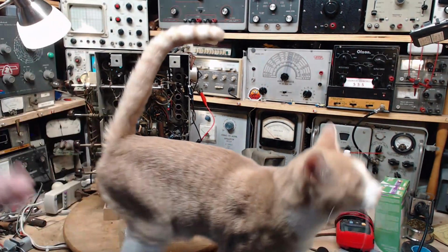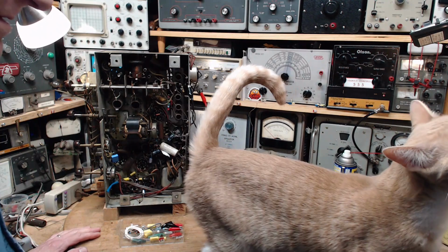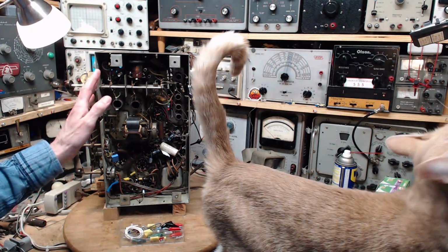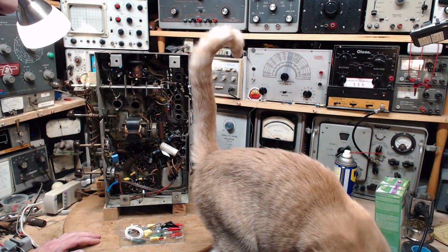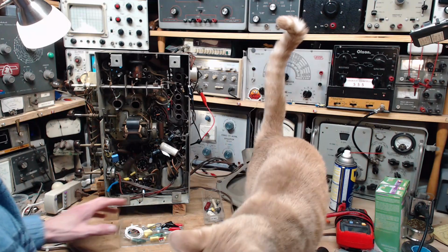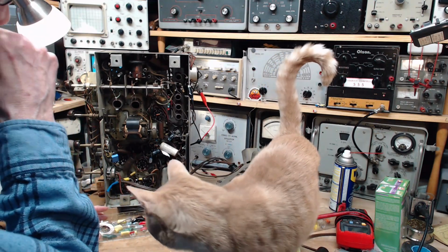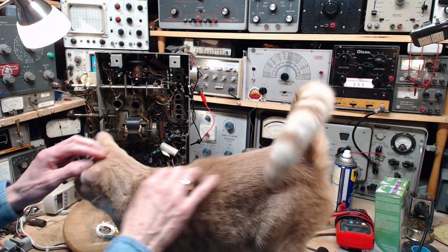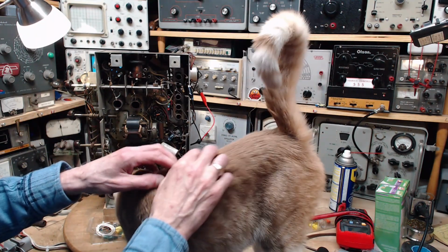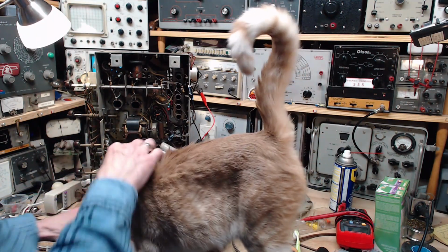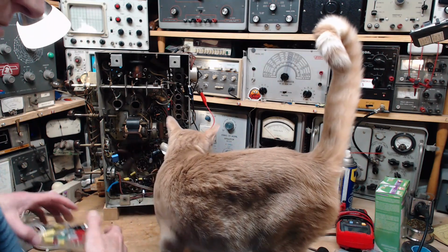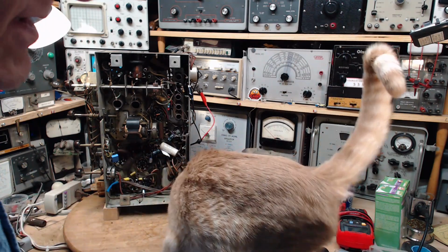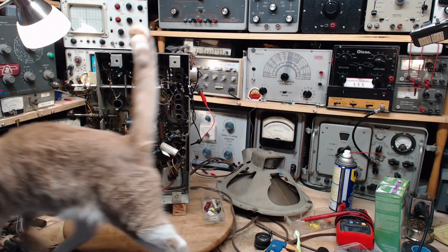Okay, so next thing to do now is to start replacing capacitors in the RF part of the radio. I think what I would want to do is try to identify any capacitor that has something to do with the screen circuit to start with. So screen circuits. So we will take a look at the schematic and see if we can find any of those guys.